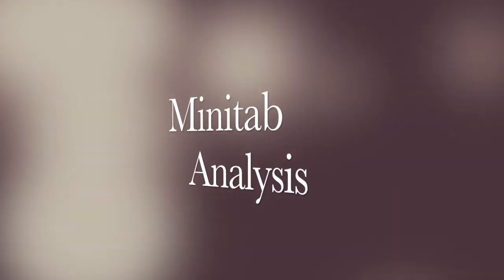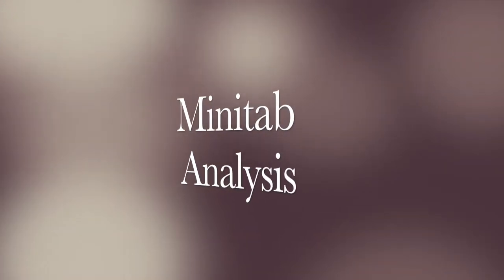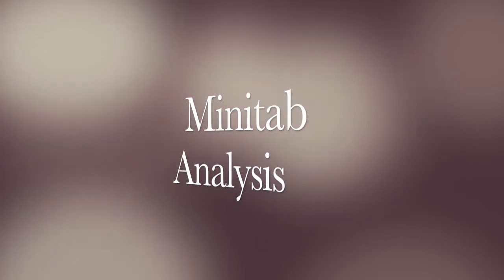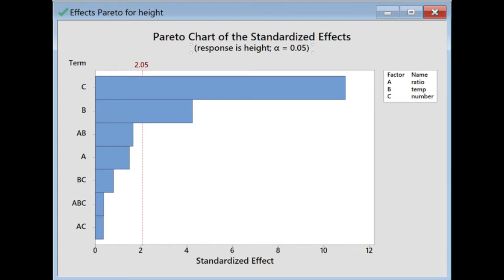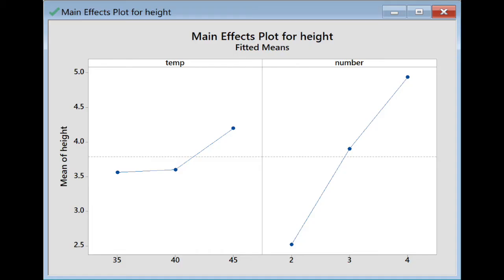After these experiments, we did design of experiment analysis using Minitab. This is the Pareto chart, indicating that only the two factors, the temperature and the number of pressing, are statistically significant because they exceeded the right line. And the main effect plot shows that the number of pressing is the most important factor.